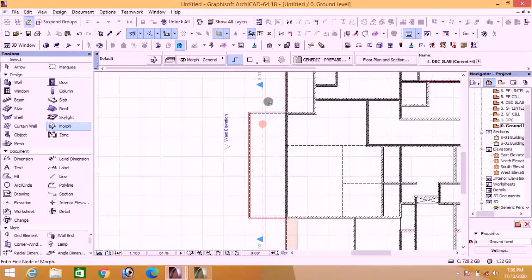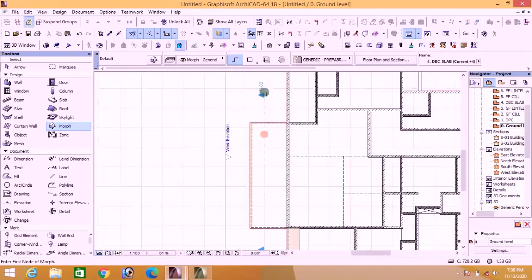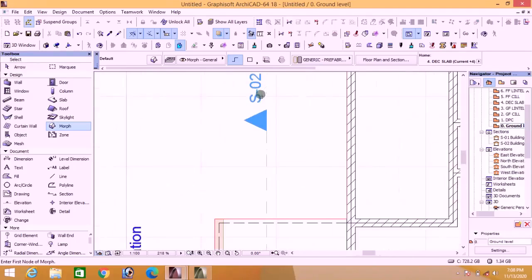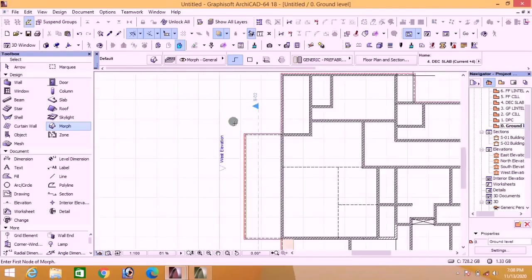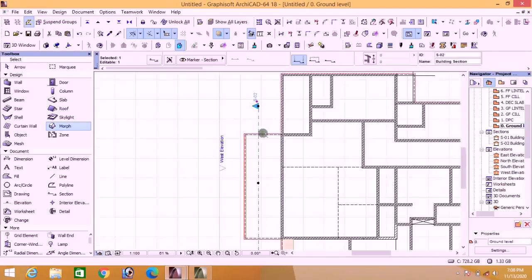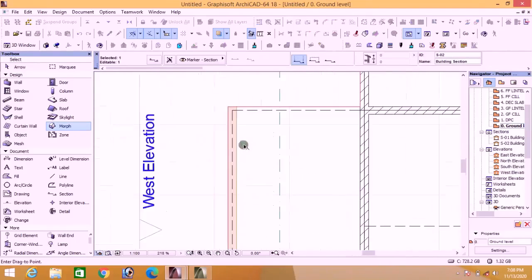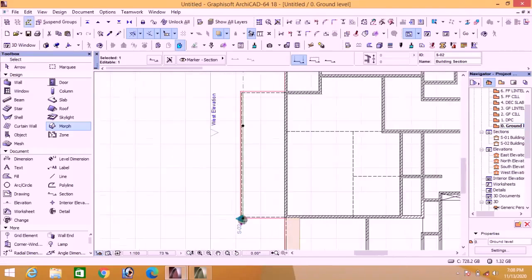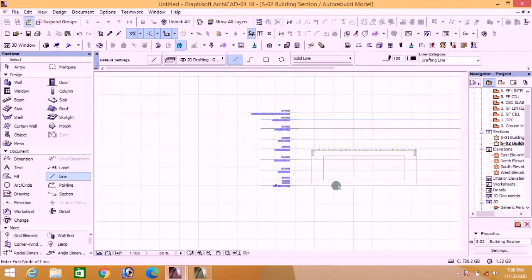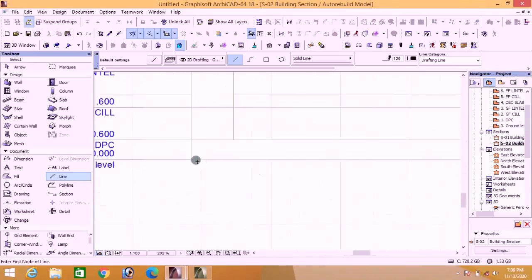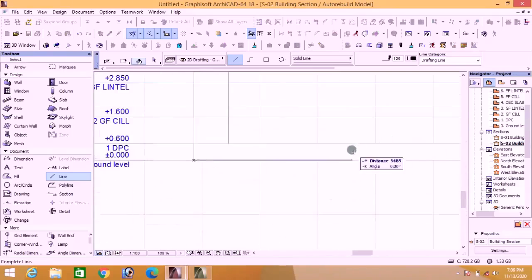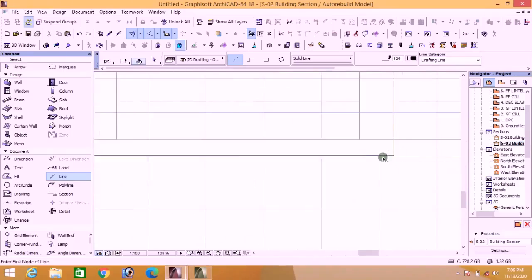Now having changed your section 02 to be focusing towards this direction, drag it close to the wall. At this spot, drag it very close to the wall. Lap it on the wall surface there. Stretch it beyond this place and open it. In this section 02, design the height of the ramp that will be there. Let's say 300.